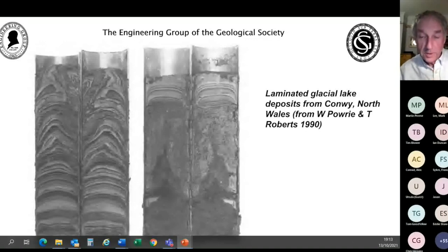Basically, that is a nozzle and venturi device. They're sometimes called ejectors, sometimes called water jet pumps. And the great thing about the ejector is that it creates a vacuum in the well, and it will also quite happily pump air as well as water. So if the top of the well is sealed and it runs out of water, it just pumps air out, and the vacuum can actually help persuade water to flow out of this rather tight soil, which does need depressurization.